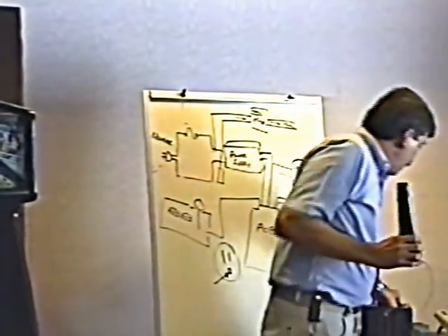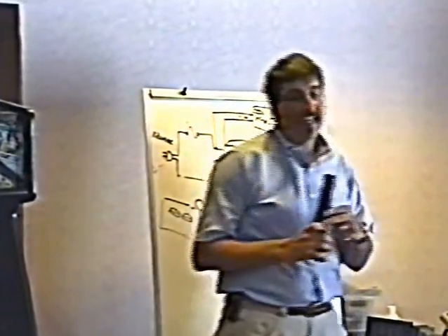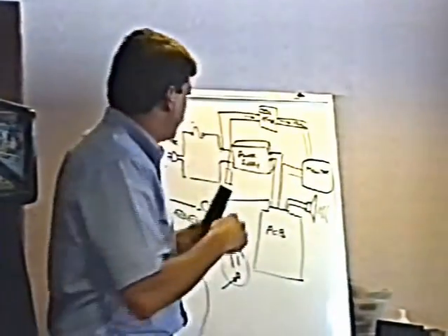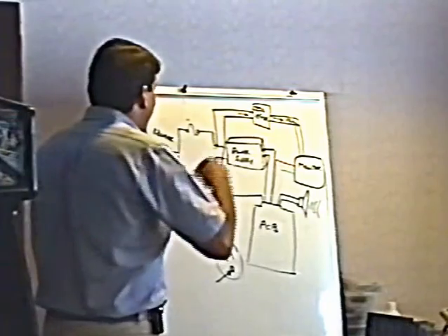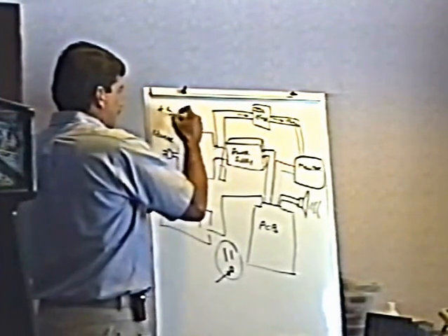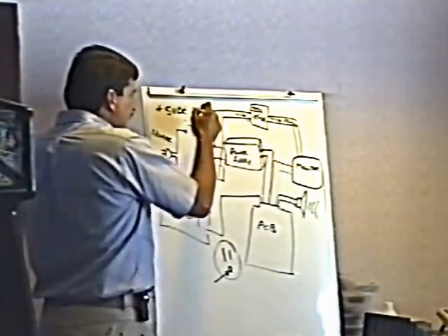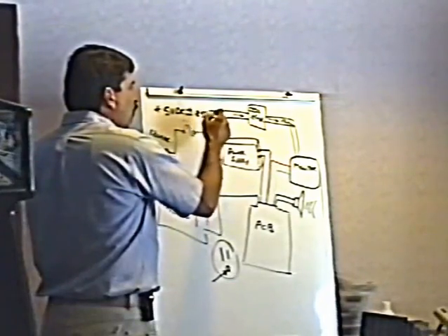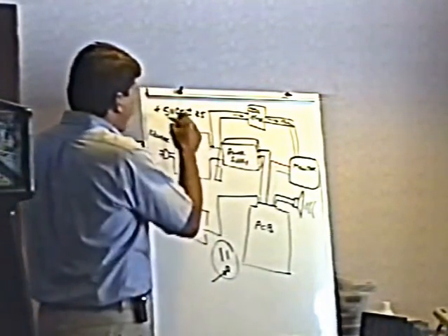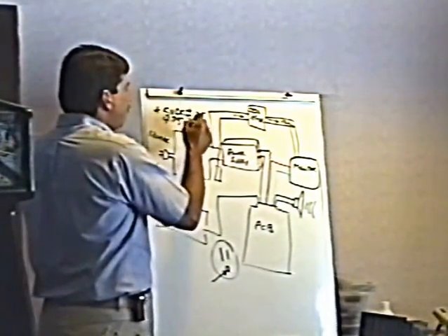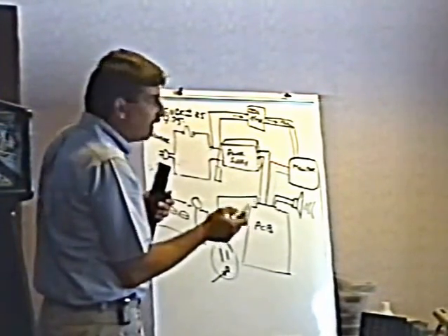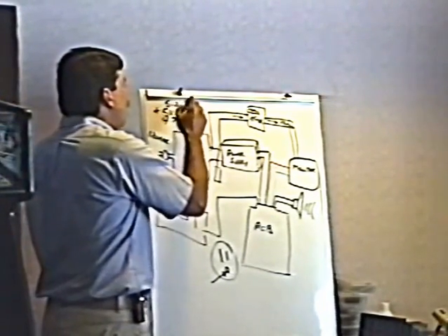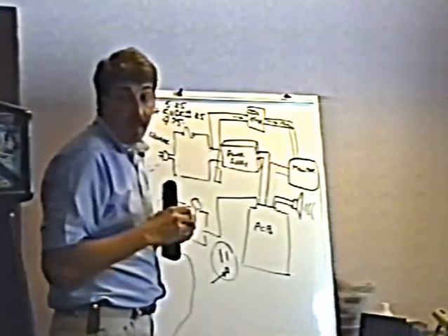It's really important that that 5 volts be exactly perfect. The 5-volt power supply has to be exactly 5 volts DC. It can only vary plus or minus a quarter of a volt, meaning that if it goes below 4.75, the computer will probably malfunction. If it goes above 5.25, same thing.